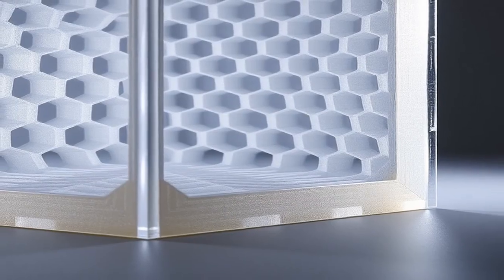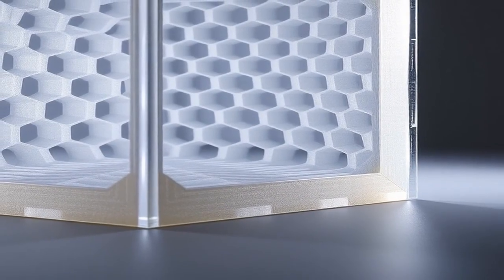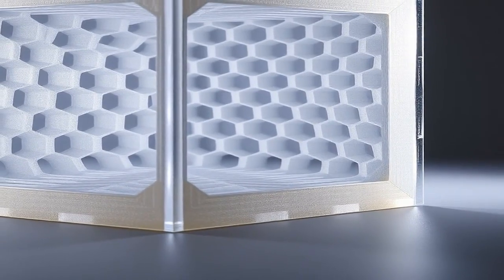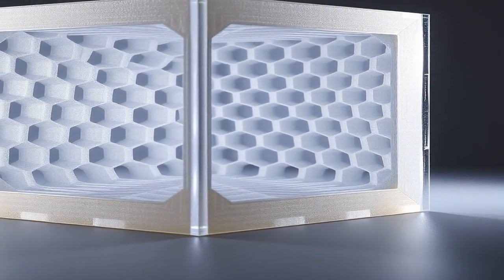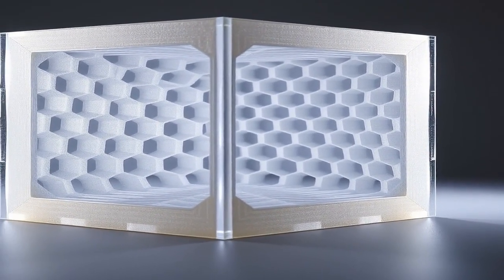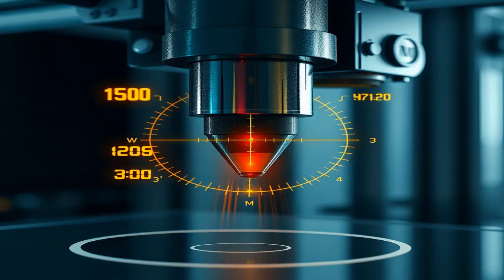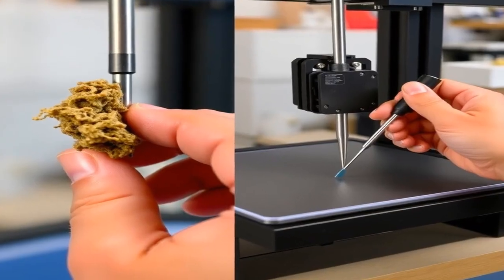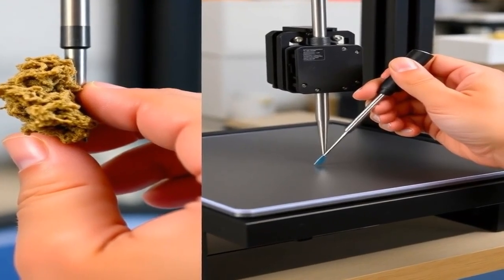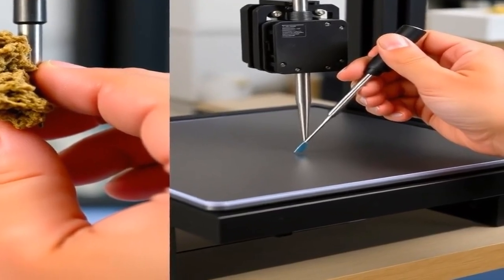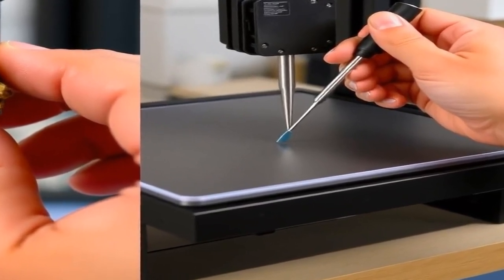Inside the object, we use infill patterns and density. A higher density provides greater structural strength, while sparser patterns save time and material. To ensure success, the printer uses real-time sensors to monitor temperature and movement, allowing for constant calibration and quality control throughout the build. When things go wrong, troubleshooting common issues like nozzle clogs or bed leveling errors is essential to getting your project back on track.